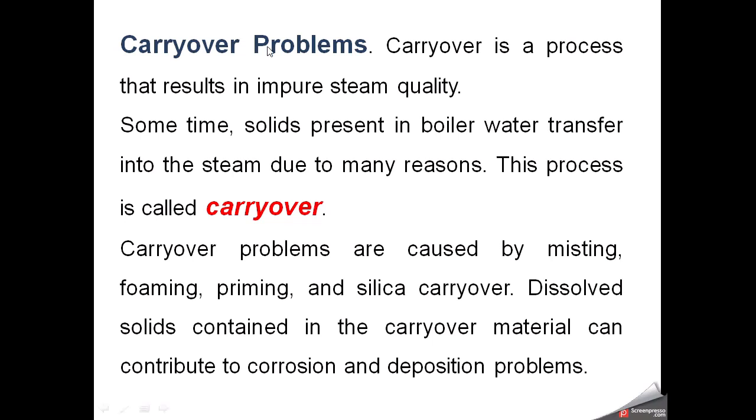So what is basically carryover? Sometimes the solids present in the boiler water transfer into the steam due to many reasons. There are some impurities, or dissolved solids, present in the boiler water, and when this water is converted into steam, sometimes it takes these dissolved solids, and then that steam carries them and creates a problem.